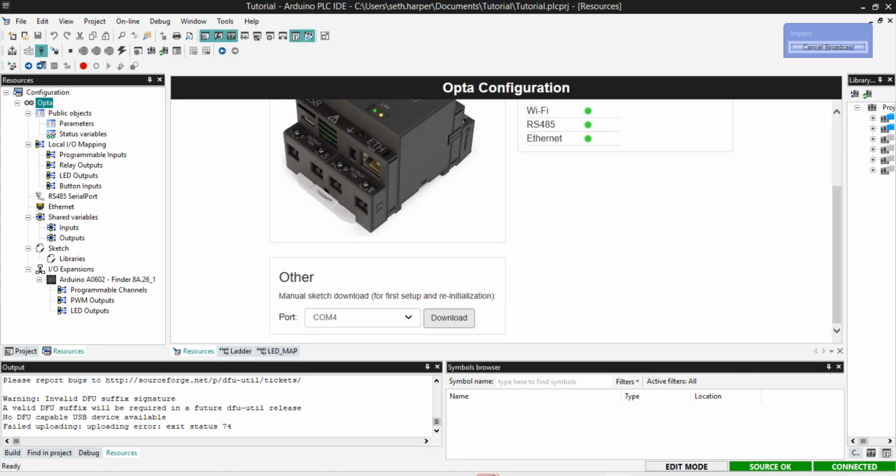So one thing that I'll try if I'm connected but it's not running my code is I'll try a warm restart, which is the green button here. And then if that doesn't work, sometimes I'll try to reboot, and then you'll have to reconnect to it. It's a whole ordeal. But I try to, in order, connect, download. If download doesn't work, I try a warm restart, and then reboot target if warm restart doesn't work. Anyway, we're good now. So my code is on there.